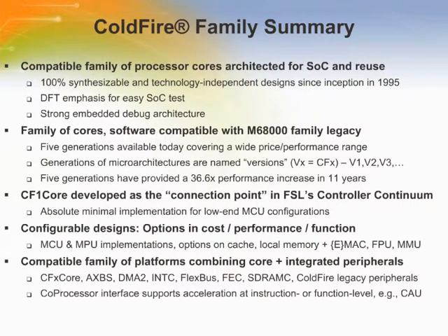From its inception, ColdFire has been designed to provide a compatible family of processor cores that are architected for system-on-a-chip design flows and reuse. The entire family has been 100% synthesizable since its inception in 1995. The cores use a standard rising edge D flip-flop implementation, which is designed to be test-friendly and easily adaptable to a wide range of process technologies. ColdFire has always had a strong embedded debug architecture which allows common development tools to be used for Freescale products as well as customer-specific designs.